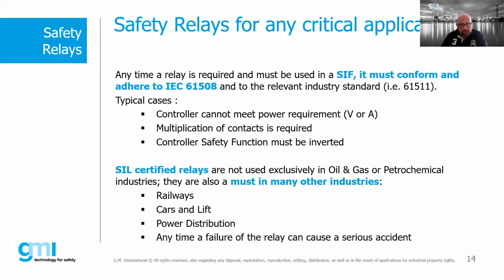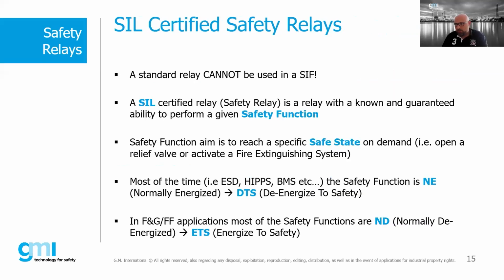In some other scenarios, safety relays are involved when the safety function that the controller must perform has to be inverted. Furthermore, in the case of smart relays, which is the most complete version, we can extend the diagnostic capability of the safety system to the entire loop, introducing the predictive diagnostic concept, which is extremely useful, especially when we talk about fire and gas. Let's go to the next.